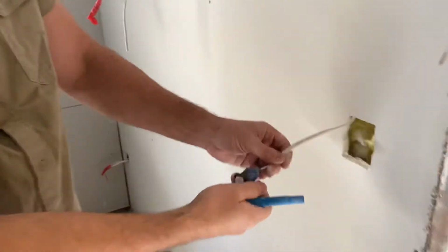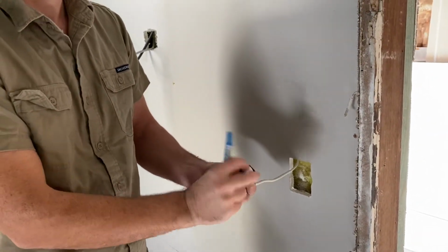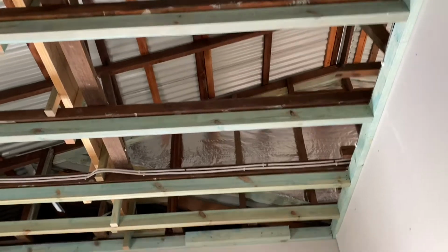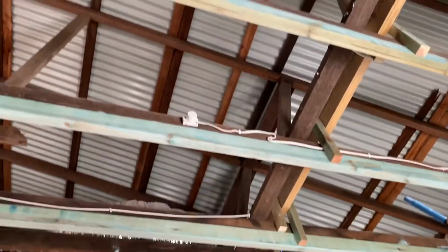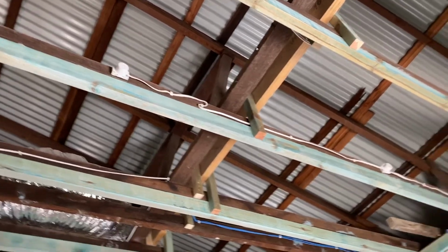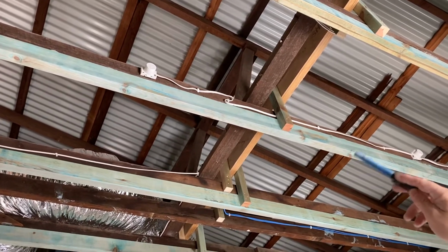Here's an example where we've wired simply just this one cable here that switches, and if we look up at the roof, you'll have to come probably on this side, you've got your power outlets there ready for the downlights, strapped and not sitting on top of the beams. That's an important one. Ready to go so you can plug those downlights in.